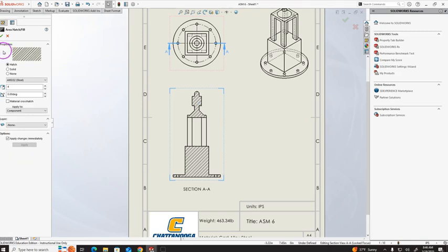To change the hatching distance, this is the option. If you reduce the value for the hatching distance, it will basically increase the distance between the hatching lines. And if you increase the hatching value, it will reduce the distance between the hatching lines. So it is opposite.